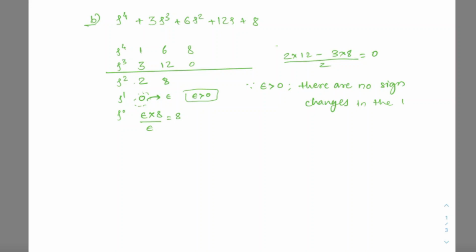Since the poles are on the imaginary axis, we cannot conclusively call this system a stable system. In the past, we have discussed this to be referred to as a marginally stable system. So the proportional controller alone cannot stabilize this system.